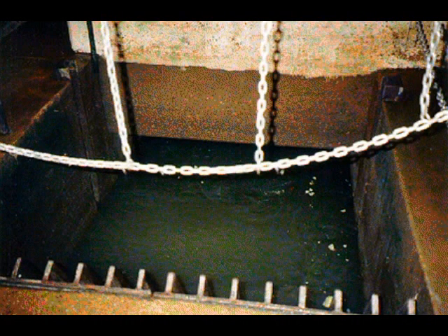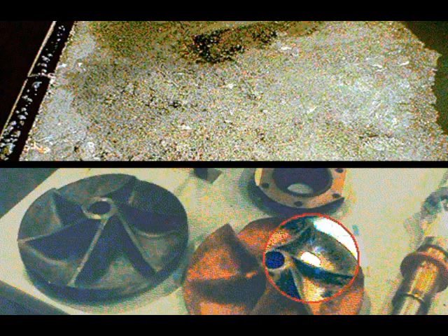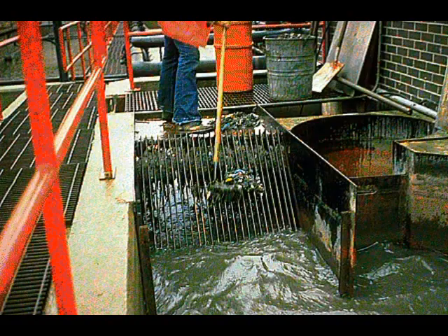Incoming wastewater, for example, has to be considered as more than just water. Wastewater may contain paper, rags, sticks, bottles, and so on. A pump can be damaged by these objects. Proper maintenance and regular cleaning of bar screens will reduce this problem, but it is still important to use a pump that is less susceptible to damage and clogging.